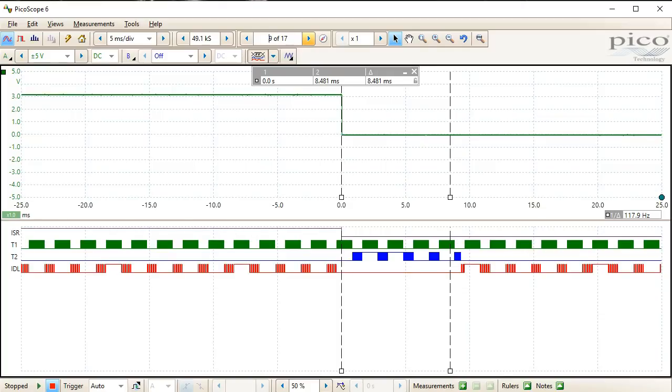This is because QXK is a preemptive priority-based kernel fully compliant with rate monotonic scheduling, RMS, and so it always executed the higher priority Blinky1 thread as long as it wanted to run, before executing the lower priority Blinky2 thread. For today's lesson, which is about understanding semaphores, I'd like you to remember that unblocking a semaphore that is waiting inside the lower priority thread might be delayed by all higher priority threads.